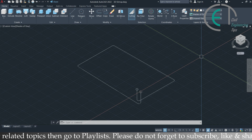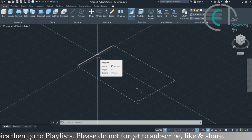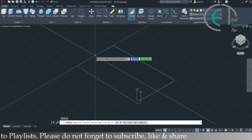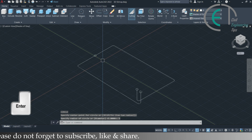Now we will draw other circles which are required in these lines to make them extruded through these paths. For that I am typing C and press enter. Then I choose the center midpoint of that line. Then I draw a circle. I give the diameter or radius as 5 mm. I am inputting 5, then press enter.